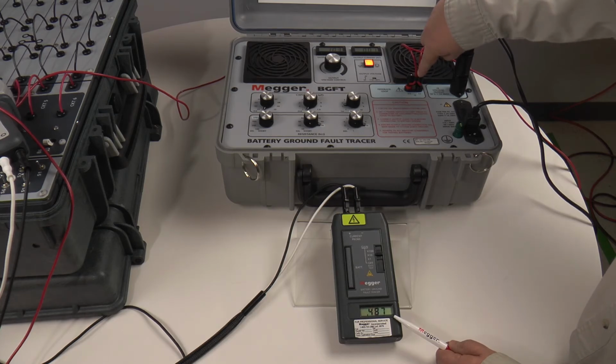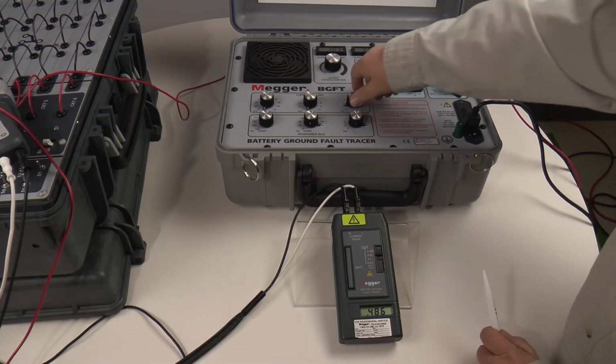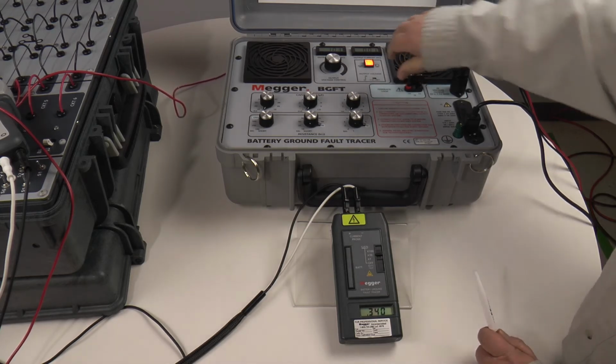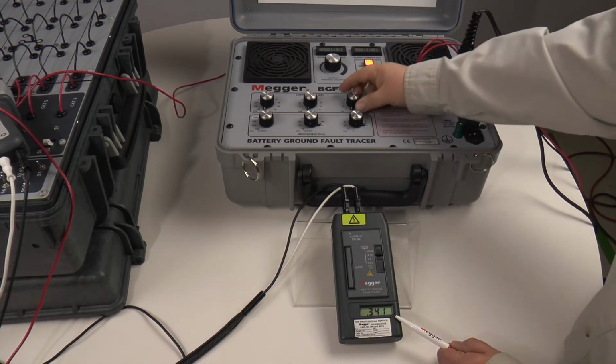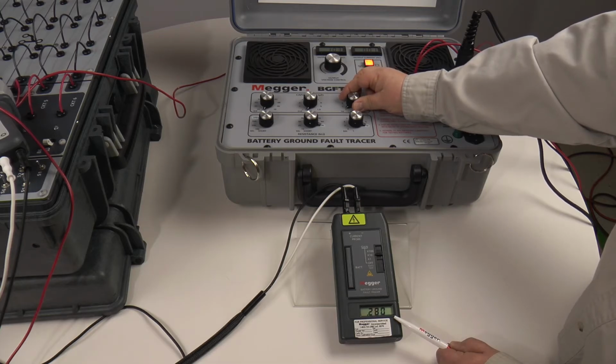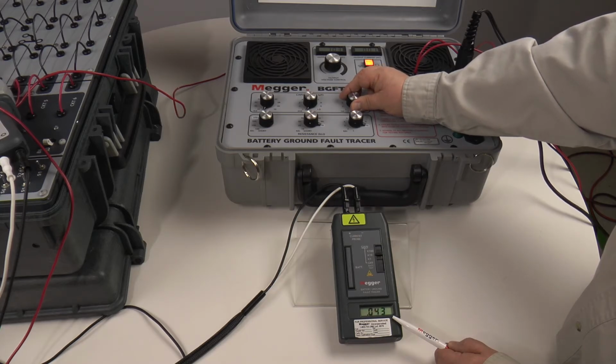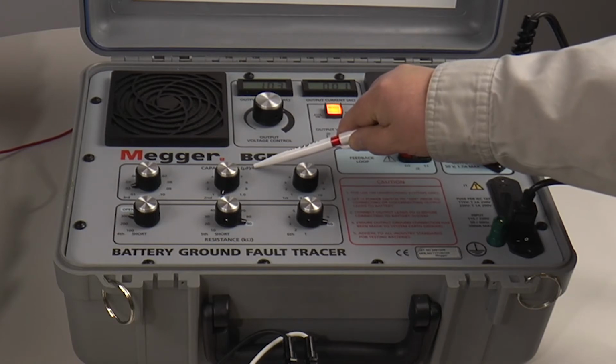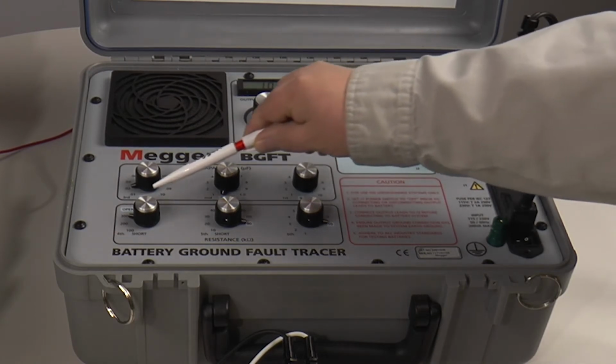Note the receiver value goes up, so we want to flip the feedback loop around. Now we see the value going down. So we are going to tune it down to the lowest reading we can get. Now we go to the resistance knobs. We see we cannot reduce the reading any lower. The reading just increases. Our capacitance is 5 microfarads, and the resistance is over 200 kiloohms.